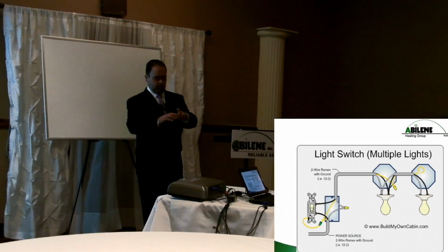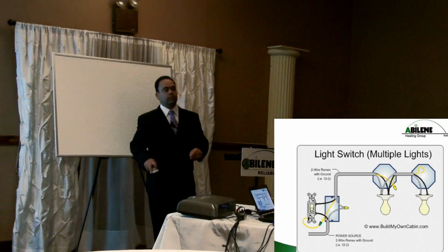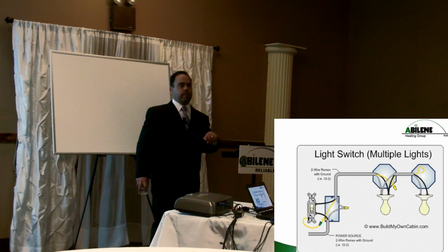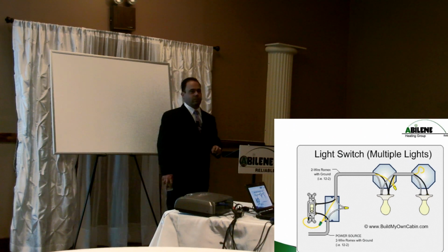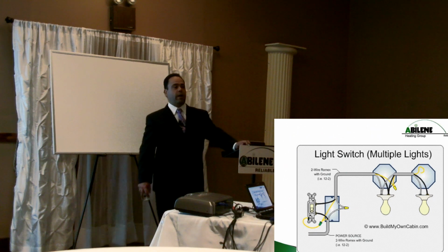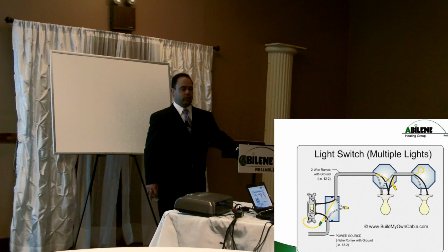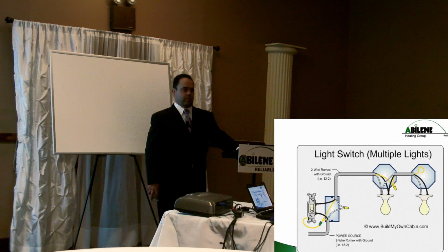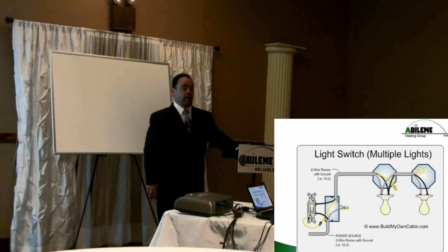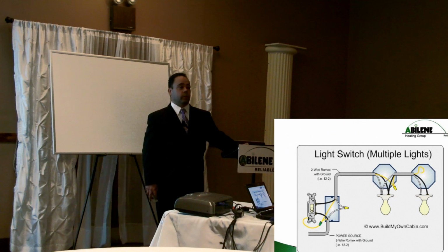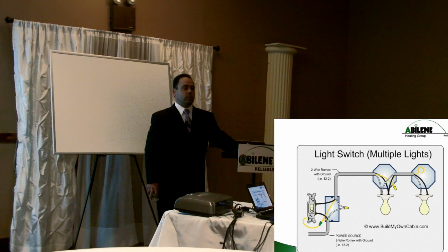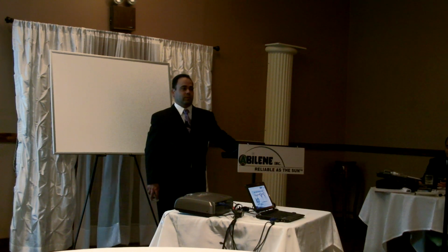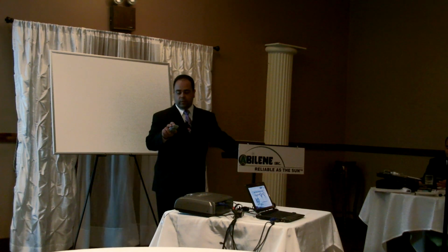How come years ago, when they wired the switch, you just ran the neutral to the switch and ran the hot? You're right. Years ago when they wired houses, they would switch the neutrals and not switch the hots. It was a bad practice. It was a very bad practice. And that's why they don't do that anymore, because it caused a lot of problems. They used to fuse the neutral at times. It's a very bad practice.